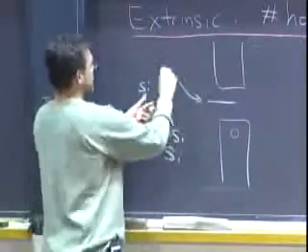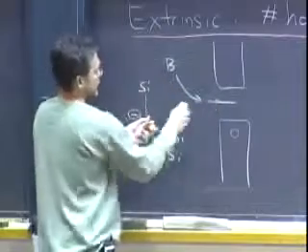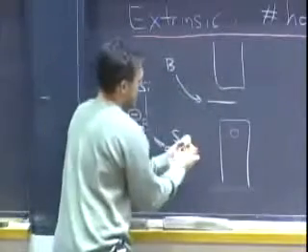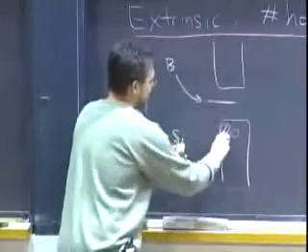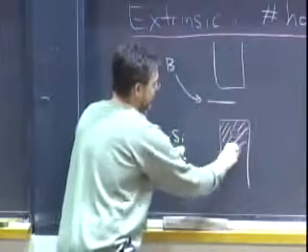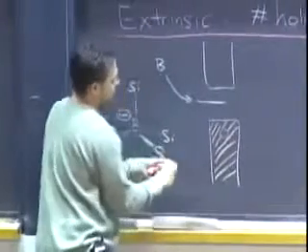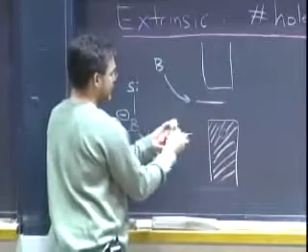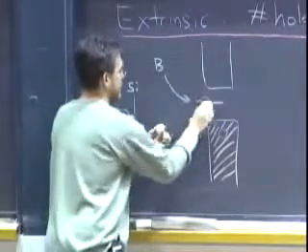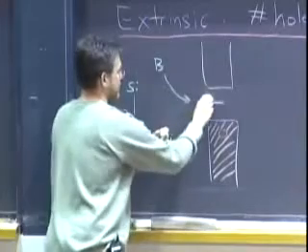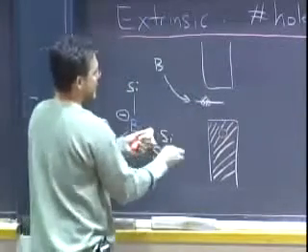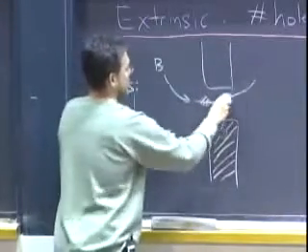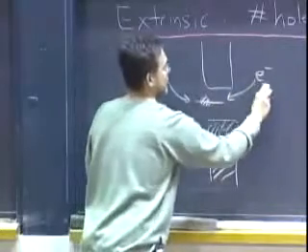What this is, here's our boron derived state here, and it needs that extra electron because it's electron deficient when you put it in there. And so an electron jumps onto the boron, we'll represent that this way in the material, like that. And this electron is fixed in position.